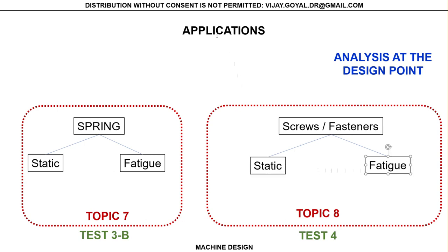Every analysis has to be done for static and fatigue. Many times, one of the biggest mistakes that engineers make is they say, well, let's study everything and design something for fatigue, and if it works for fatigue, it works for static. It's not quite correct, because think about this. I got this pen, right? And I'm constantly applying load. Now, the load is not completely applied constantly over a long period of time.